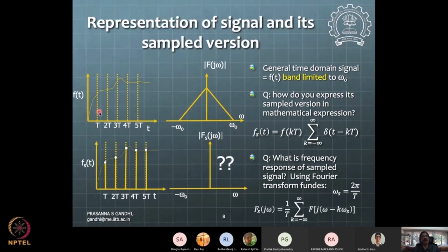Now, when I say that in the limit the period of the signal goes to infinity, this becomes like a continuous signal, and instead of these discrete parts, I also get a continuous representation here. That is a sense one can think about. So the Fourier transform is nothing but the Fourier series in the limit as the period of the signal goes to infinity. A period of infinity means the signal is not periodic, so a non-periodic signal has infinite period. That is the sense we can see for the Fourier transform.